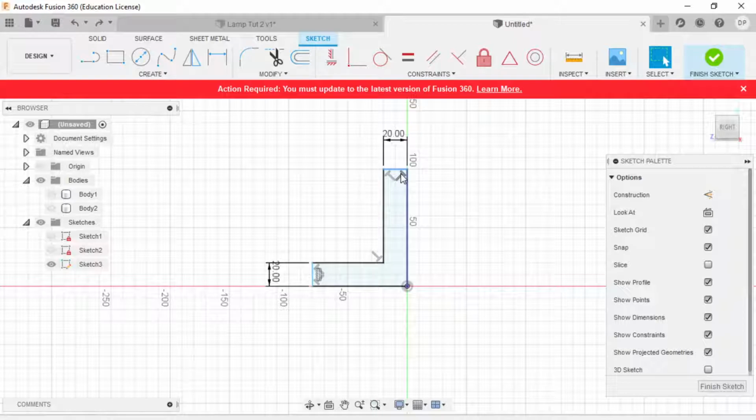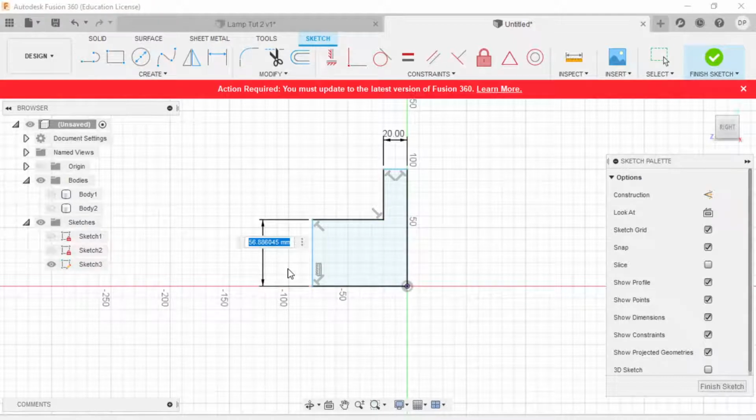This is a solid, a flat piece of aluminium that's bent in a machine at a right angle. So it should have a constant thickness. What you can do is, you have these two dimensions over here. Right now they're both 20 millimeters, but let's say they're clearly not equal in length. Instead of writing in your dimensions, let's say I'm going to make it 2 millimeter thick aluminium. I can write 2 and 2 and it can make it.